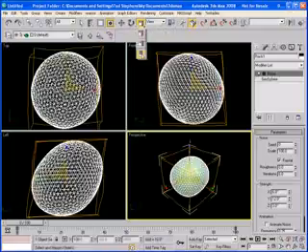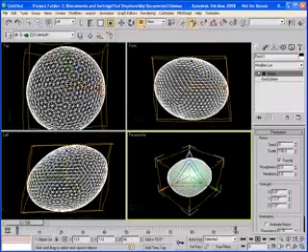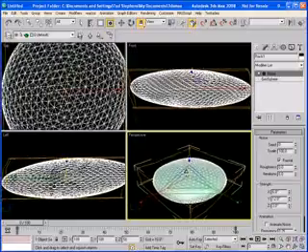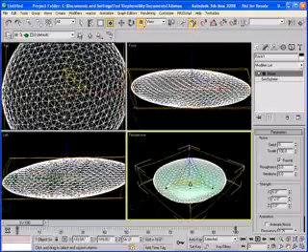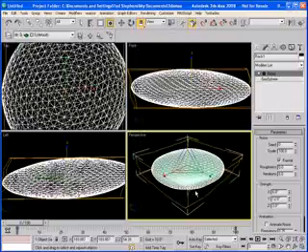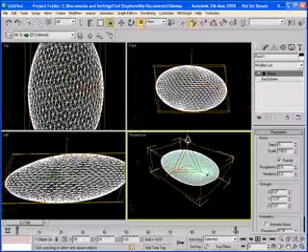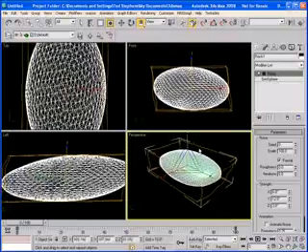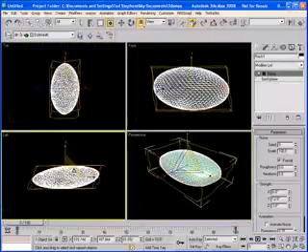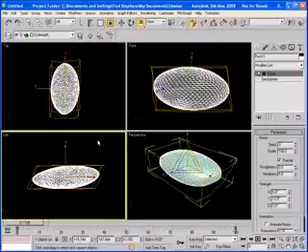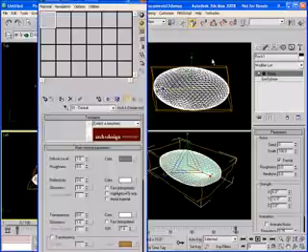And now I'm going under my Scale command here, and the little flyout, I'm going under the last scale, so it's the Squash type of scale. Squash basically keeps the volume of the geometry in place. So I'm going over the z-axis and just left clicking and basically squashing that along the z-axis. And you can work with the different axes on here and just squash them in along different axes. If you go on one of the triangles, you're going across 2 different axes. So again, we're just trying to add some randomness to it so it looks more like a rock.